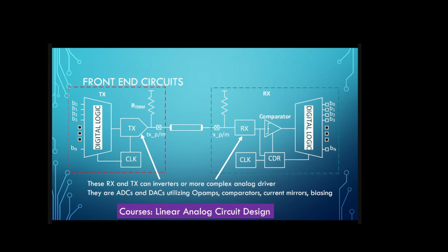Anybody any answer? You can only call it linear when we bias it on a linear operation. Okay? If you learn about op amps and other places, there's a biasing concept. There's a concept of DC analysis. You bias your circuit such that we can model that analog circuit as a linear block. Okay, that's a very important concept. It's a digression, but if you take these analog courses, pay very close attention to how they are actually being used.